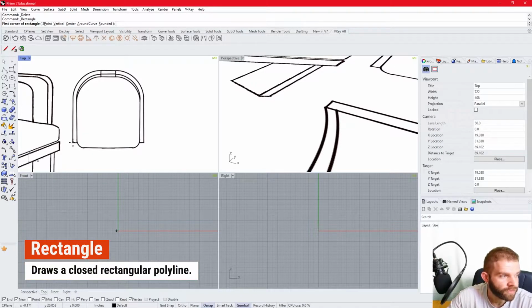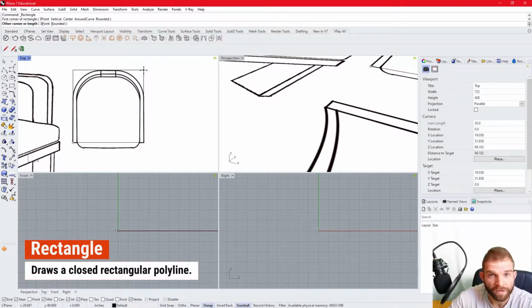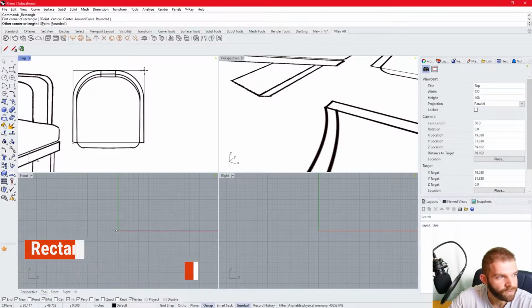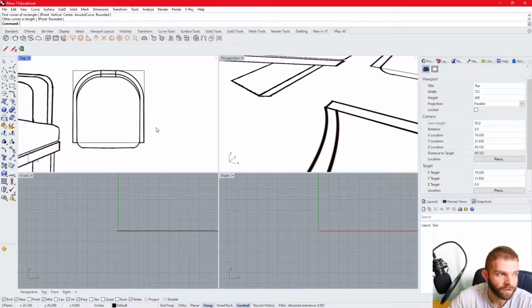Now, I'm going to draw out this rectangle. I'm going to start somewhere that's easy to reference, such as this corner right here. I'm going to draw out this rectangle and pick another point that's easy to reference. Since my box is getting drawn out, I can align it to the other edges. Now, here's one very important tool that comes along in Rhino 6 and 7, which is that you can control individual elements of any curve, line, surface, or mesh.